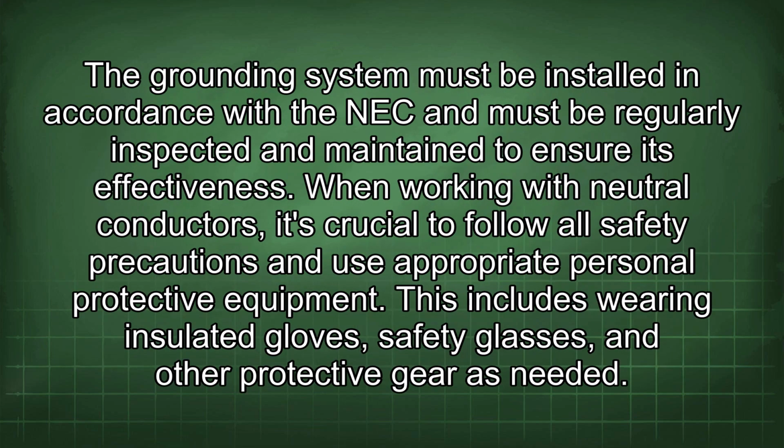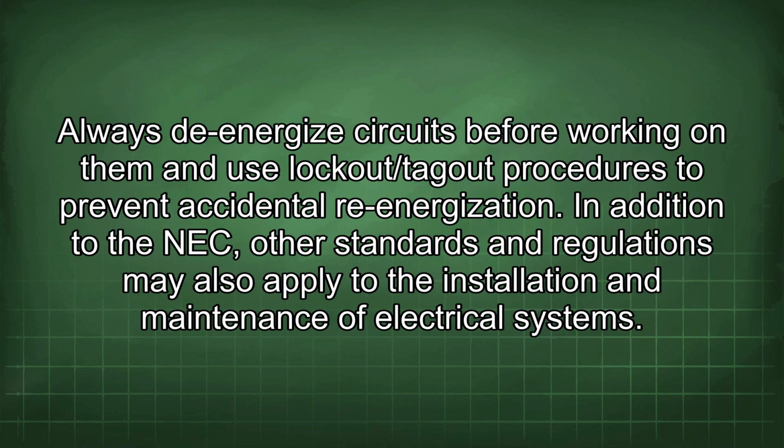The grounding system must be installed in accordance with the NEC and must be regularly inspected and maintained to ensure its effectiveness. When working with neutral conductors, it's crucial to follow all safety precautions and use appropriate personal protective equipment. This includes wearing insulated gloves, safety glasses, and other protective gear as needed. Always de-energize circuits before working on them and use lockout/tag-out procedures to prevent accidental re-energization.